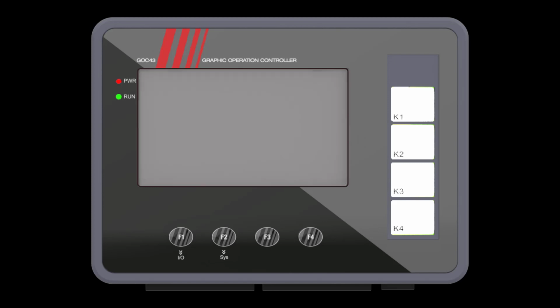In addition to IO extension unit status monitoring, you can also monitor status of digital IO points on LCD screen. You need to enter IO monitor screen for this purpose. To enter into IO monitor screen, press F1 key on main unit for 3 seconds.